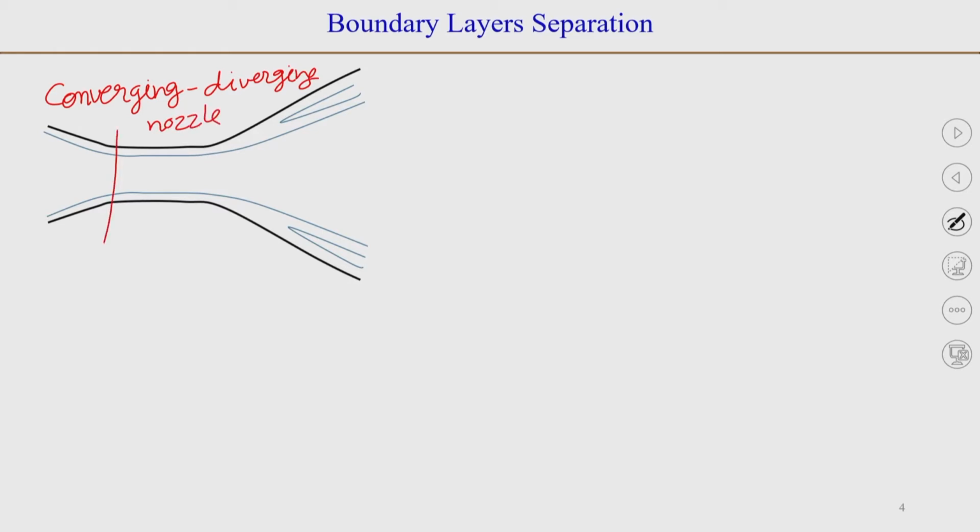So, in this region the flow is accelerating, because the area available for the flow decreases. So, the velocity will increase and the flow will accelerate as you move along this direction, and dP by dx will be positive here. So, you will have the velocity profile, for example, here that will be